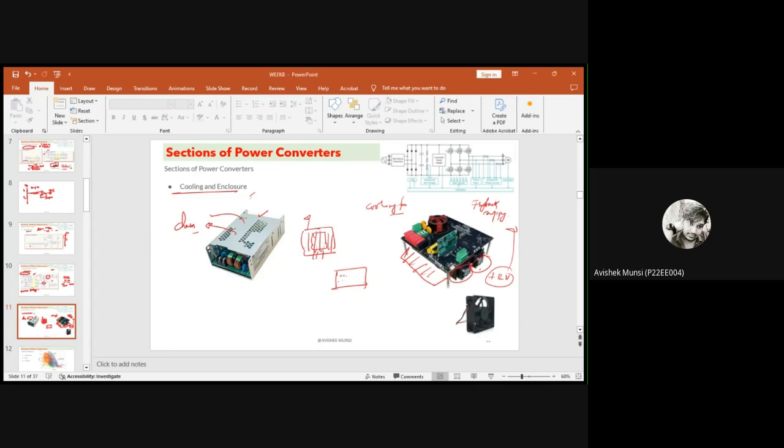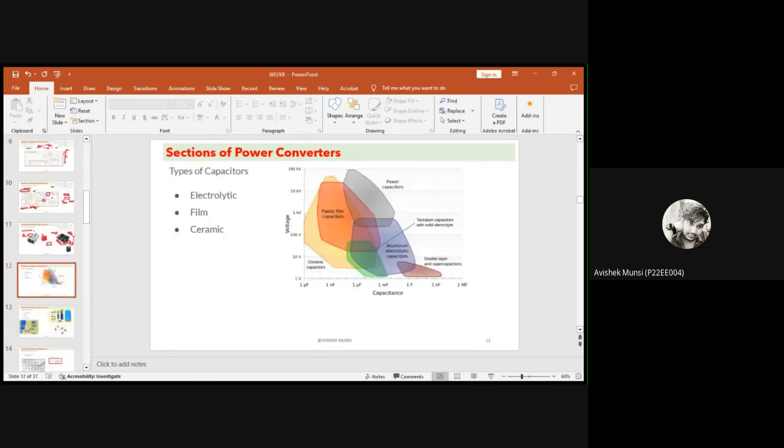Fine. So, next part where we move into it is the selection of capacitors. While designing a power converter, you require capacitors, resistors, inductors. Inductor design we had discussed previously. What are the basic features we require for designing inductors? We discussed it: the core, the wire, how much current is flowing. That is the main thing while choosing an inductor. You have to think about the current, how much resistance it has, the equivalent resistance. You should take that into account.